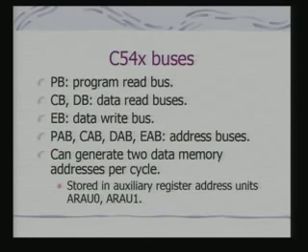The most interesting feature of this is buses, the number of internal buses that it supports for accessing data and the program. So, I have got program read bus, data read bus, data write bus, and these are all address buses. So, you can see that since I have got these address buses, all these operations can actually be overlapped in time.